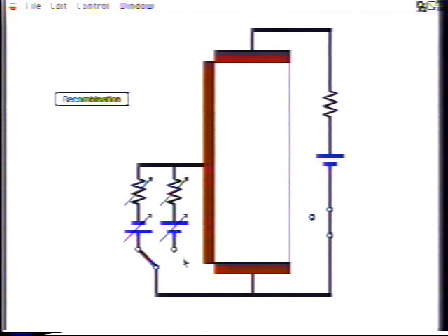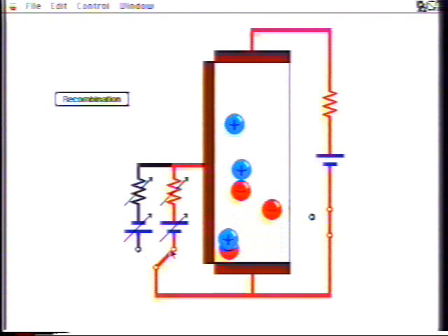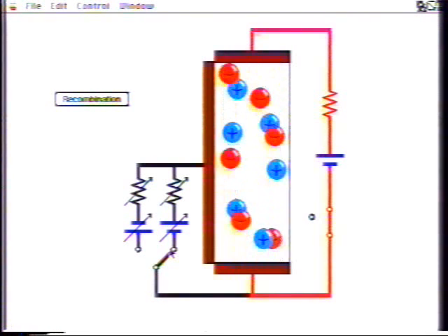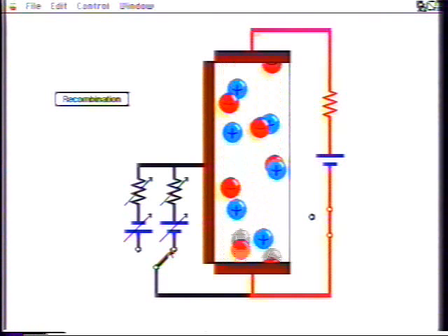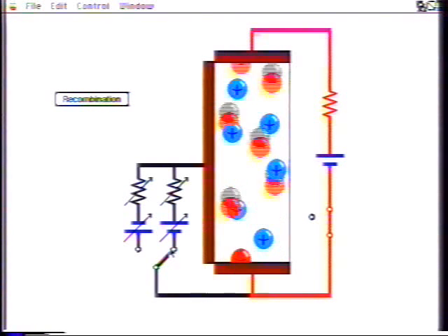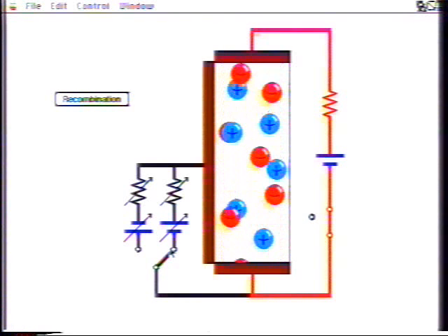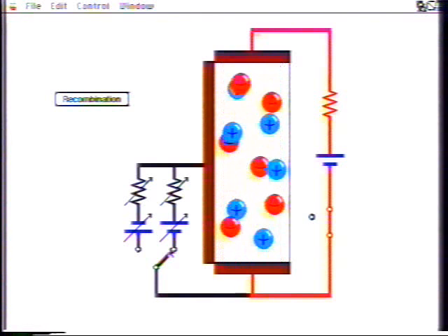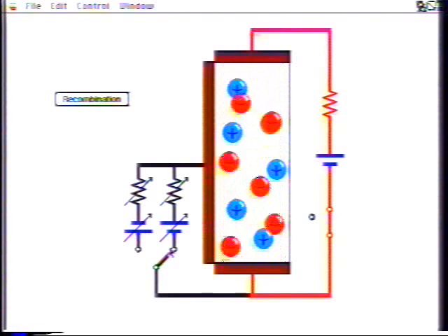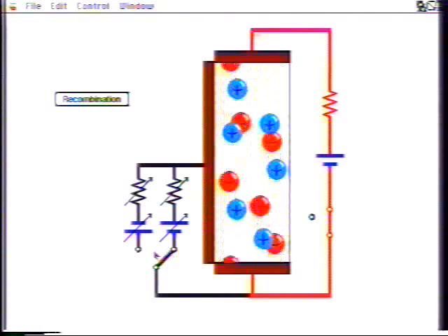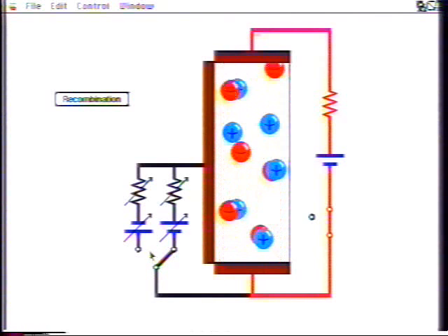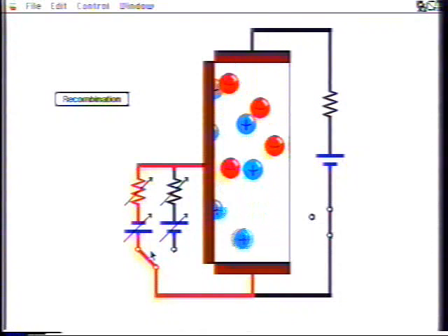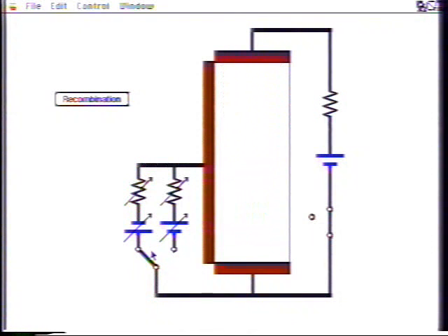When positive charge is placed in the base region in the form of majority carrier holes, an equal negative charge of electrons is injected into the base region from the emitter junction. These electrons are available to carry current through the base region and constitute the steady state or DC collector output current. To open the BJT as a switch, the positive hole charge must be withdrawn from the base terminal, eliminating further electron injection from the emitter, turning off the collector current.